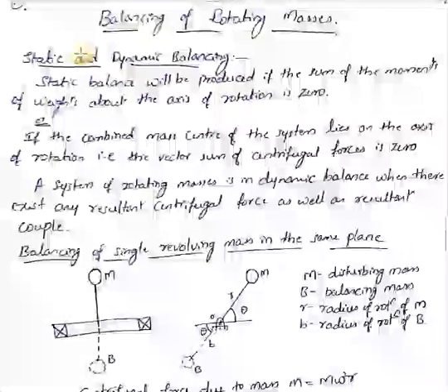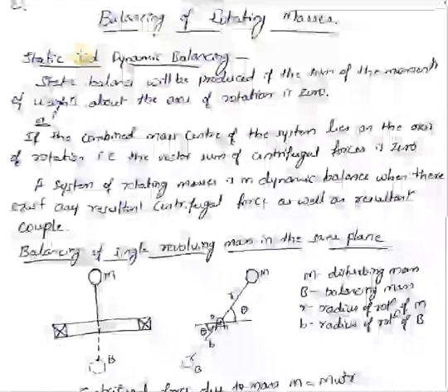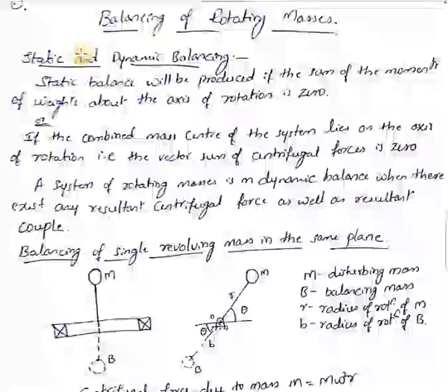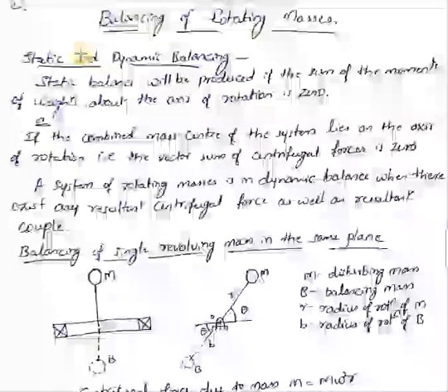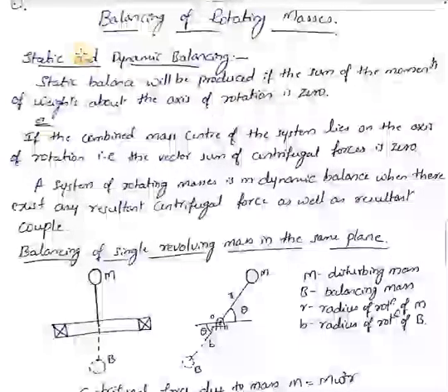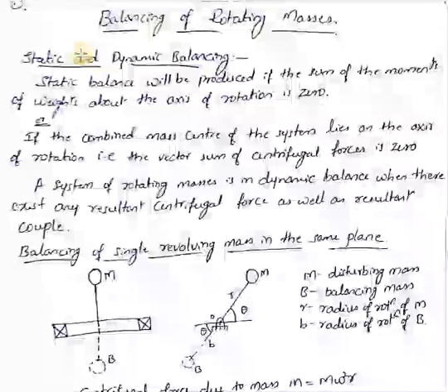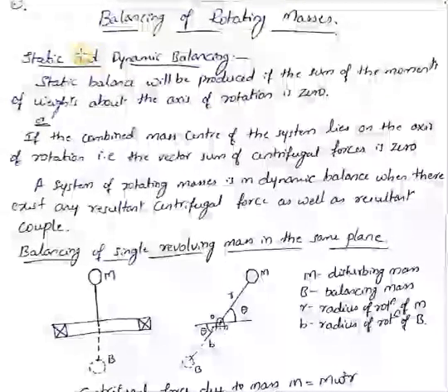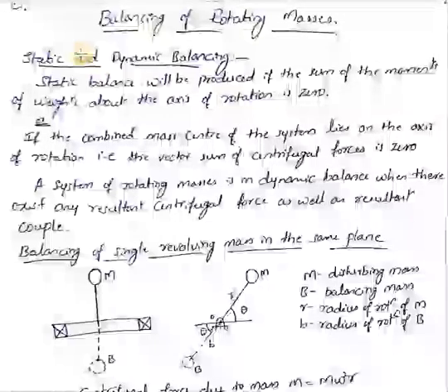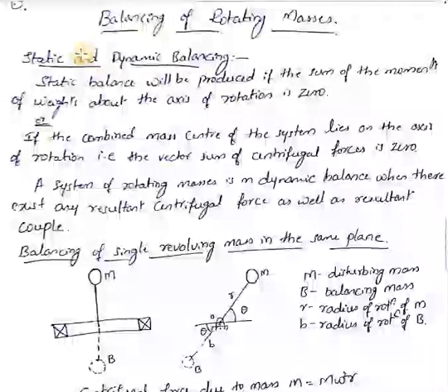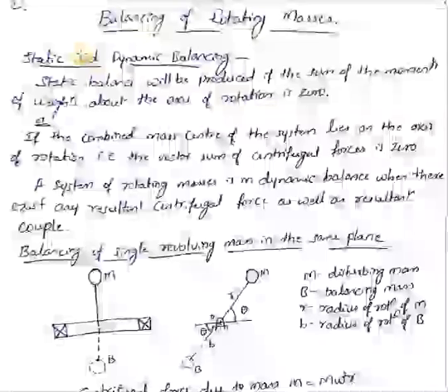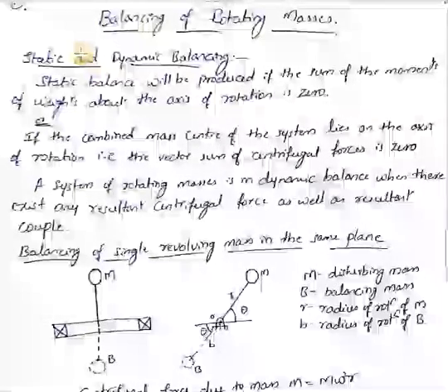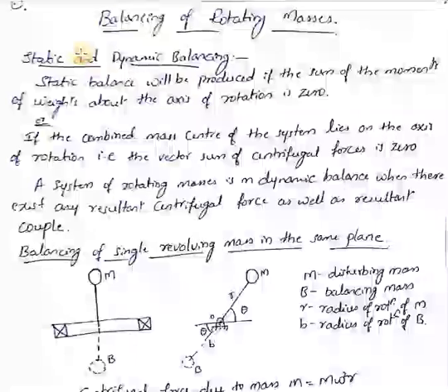Otherwise, dynamic forces are set up, and these forces not only increase the load on the bearings and stresses in various members, but also produce unpleasant and even dangerous vibrations. These are harmful to life as well as to the performance of the machine. That is the reason why perfect balancing is required.